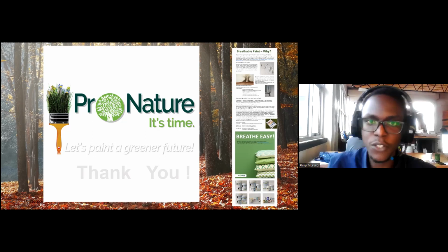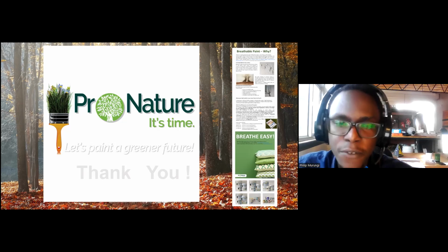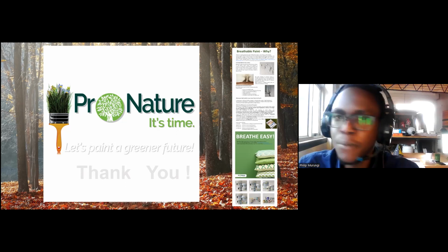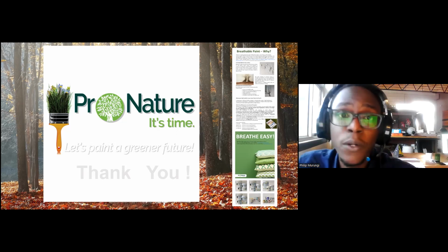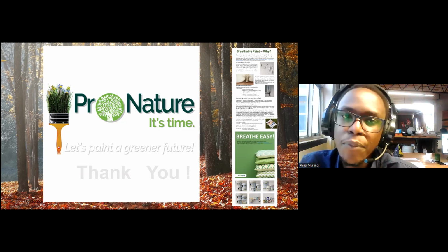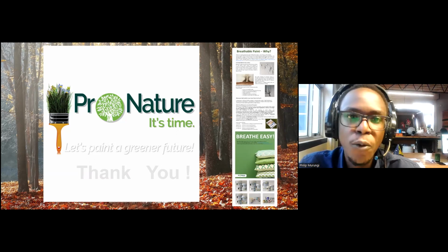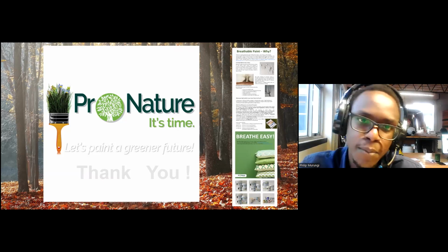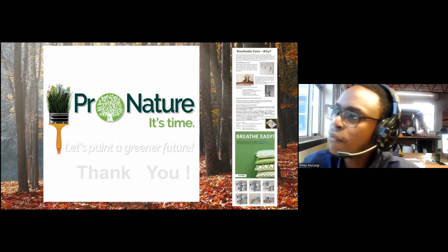That's an interesting question, and of course, it depends on the difference of absorption and desorption between these two materials. Your specific example of brick and lime is even more interesting because there's a project we're working on recently, and you have these walls which have been basically compromised by rising damp, and we've opened up the foundation and we wanted to basically protect them. So we can't put in a DPC to prevent the water going higher.